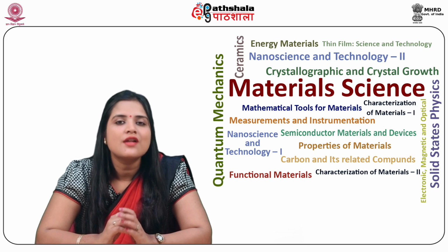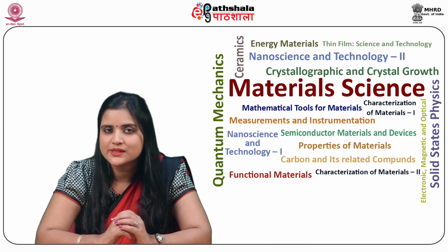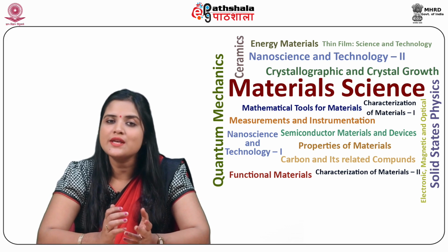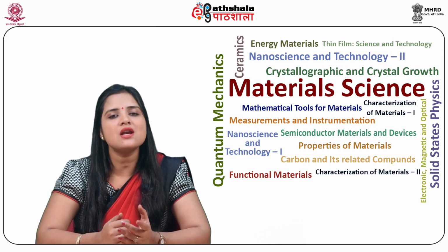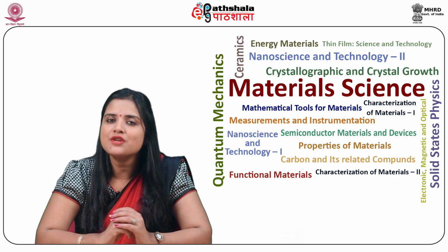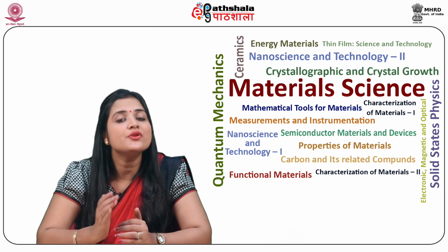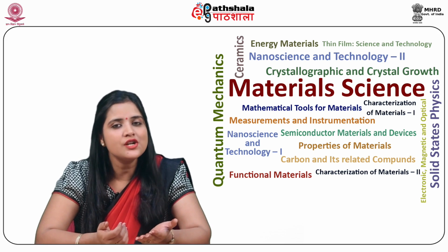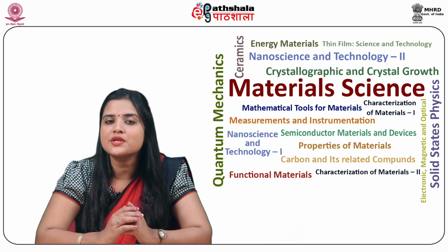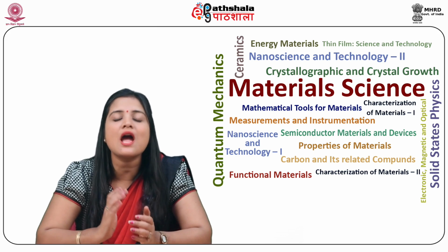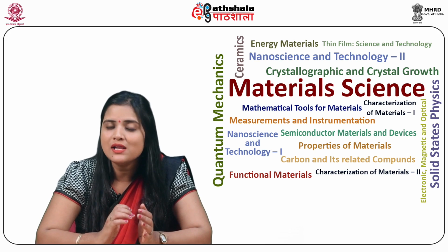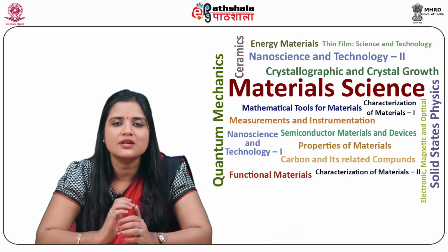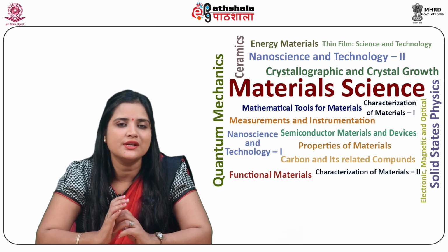Let us discuss the classification of filters. Electrical filters may be classified in various categories as analog or digital, active or passive, and audio or radio frequency. Analog filters are the filters which are used to process analog signals using analog techniques, while the digital filters are used to process analog signals using digital techniques.